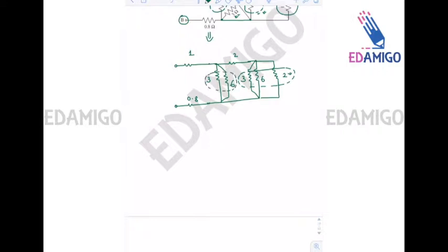So first of all, let's see what is 6 parallel 3 equal to. So this resultant will be 1, 0.8, A and B. Okay. So 6 and 3 parallel. We know that the result is 6 multiplied by 3 divided by 6 plus 3. That is 2. Right? 6 into 3 is 18. 6 plus 3 is 9. Okay. So this is 2.